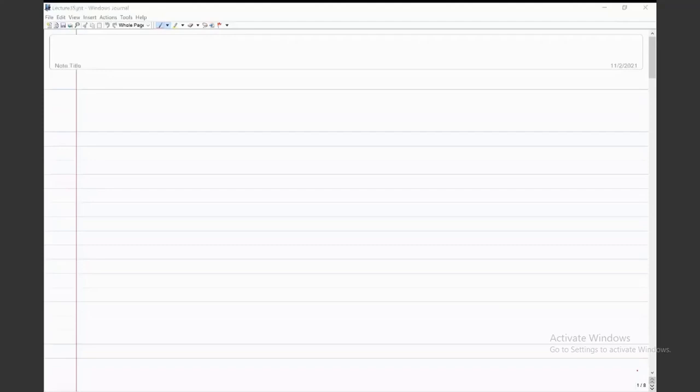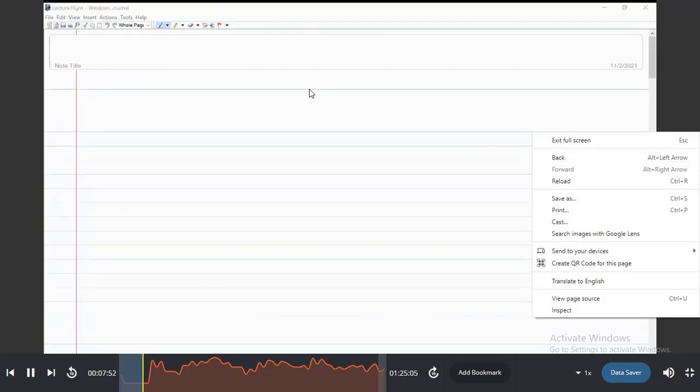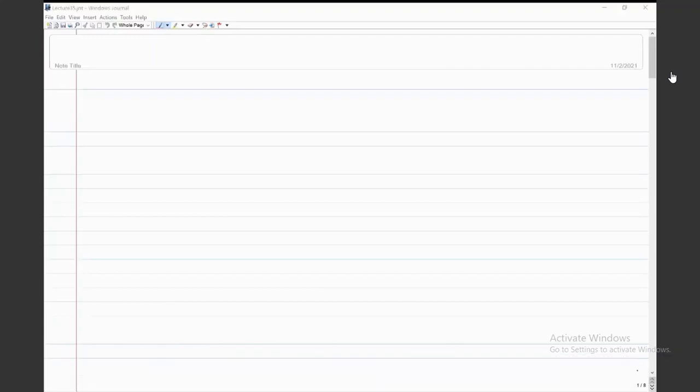Sir, I have a doubt on this gap. In the last class, you defined that if U3 minus U4 is greater than G, then the gap is closed. Is the G value some penetration which is happening? Or is it not the penetration, but the initial gap between the two nodes? When this gap is closed, will there still be some distance between the two nodes? I'm not able to exactly understand. No, when the gap is closed, the distance between these two nodes would be 0.